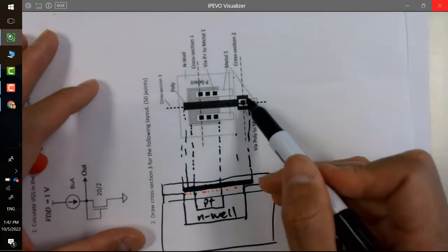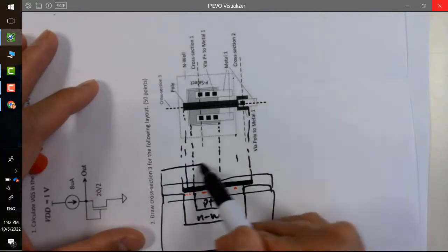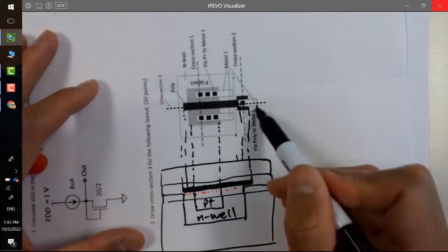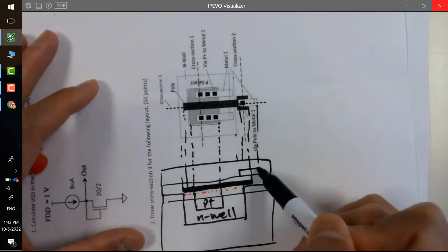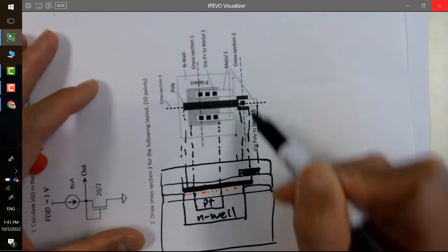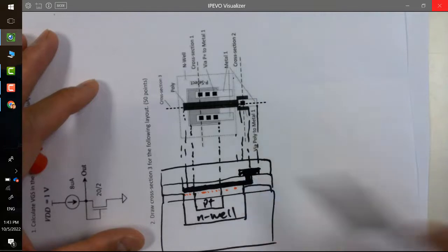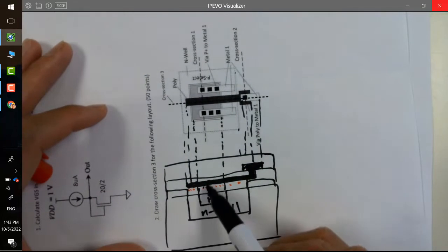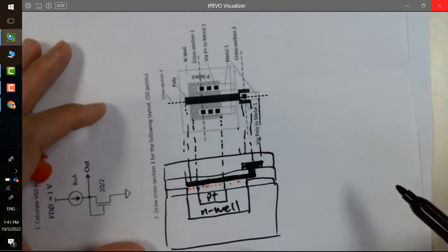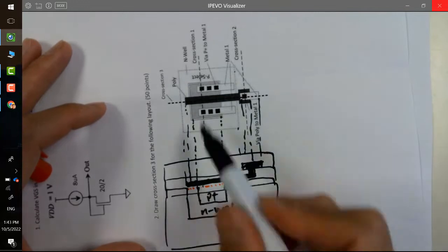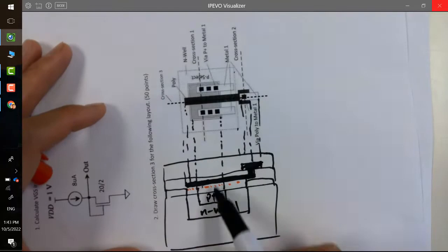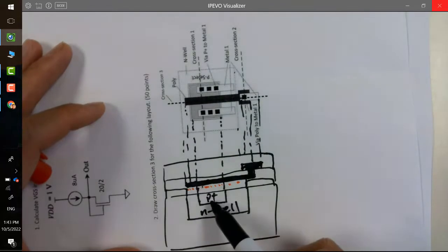And then what is this material? Metal 1. So we need another layer. And just draw metal 1. It's this long. So this is metal 1. And here's a little via here. Right, and that's it. Some of you just drew a lot of vias here. Doesn't make sense, right? The poly shouldn't have any, there's no via by looking at the layout. And also the gate shouldn't have any direct connection to the P plus.